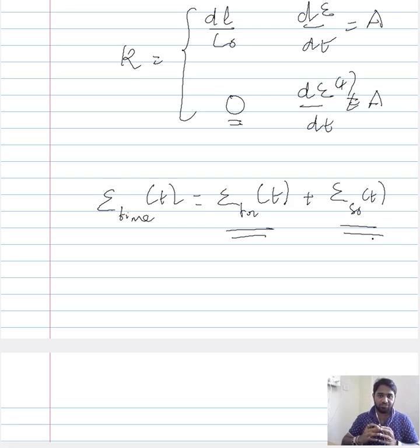So the initial stage for him was the time independent zone, and that is for us the instantaneous creep, wherein the increase in strain is exponential with time. The second zone, the time development zone, comprises two subzones, one wherein there is a noticeable change in the slope, the other wherein there is not much change in the slope. So this is how he vaguely differentiated them, or the pioneering expression had this understanding.